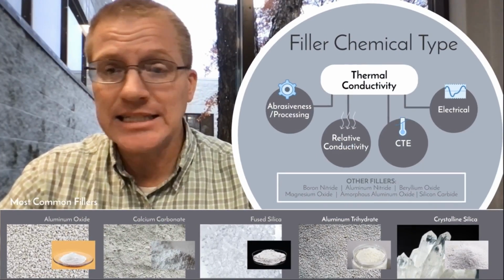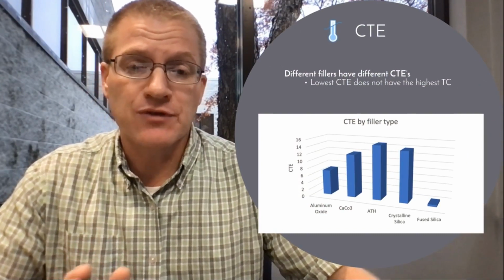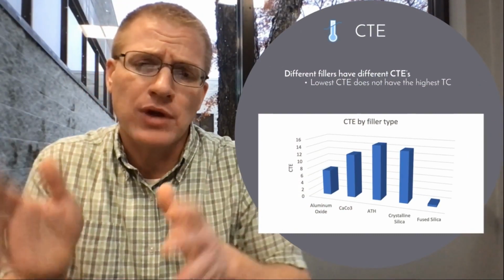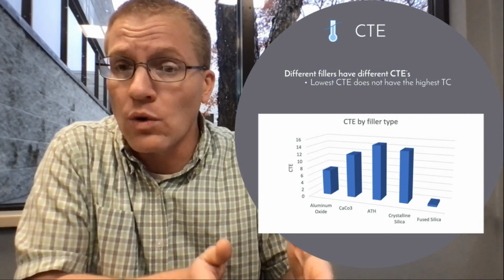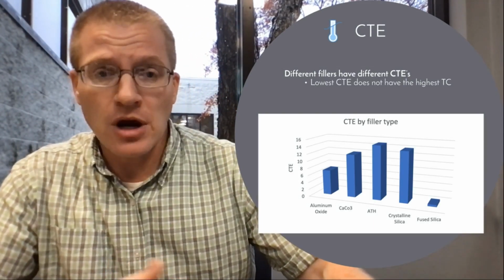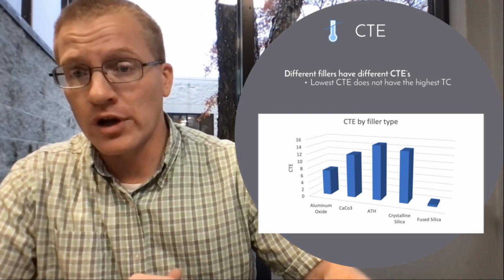All right. So from there, let's look at the CTE of these different minerals that are used. This is actually the CTE of the specific mineral. As you can see, aluminum oxide is really low. We're going to talk a little bit about why this is important in the final polymer, but really it translates into the polymer also having a lower CTE, all right? And you see how these other calcium carbonates are higher, aluminum trihydrates higher, but fused silica down here, you see how that is very, very low.